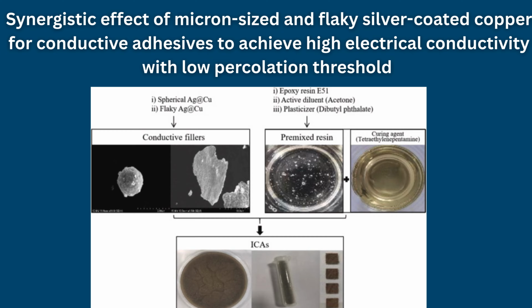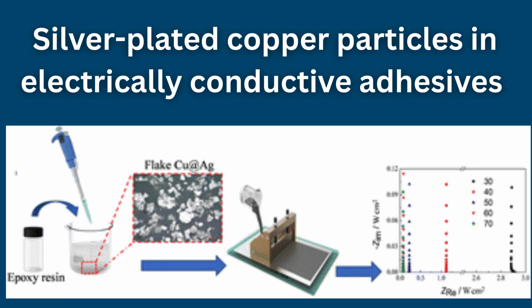Long-term thermal exposure also highlights the advantage of these particles. In adhesives filled with pure copper, oxidation forms near the particle surface and increases electrical resistance. In contrast, silver-coated copper particles prevent oxygen diffusion and maintain stable conductivity. Electrical performance also depends on curing conditions.